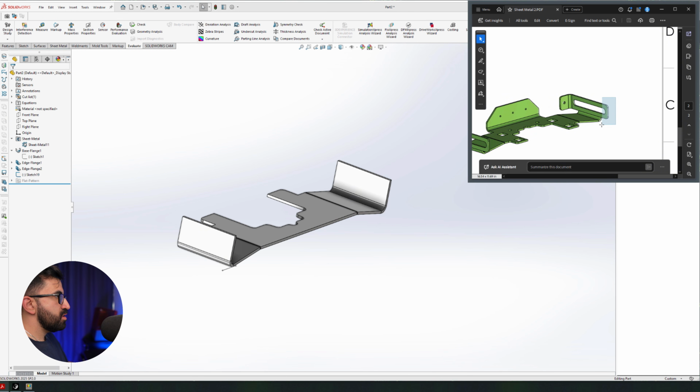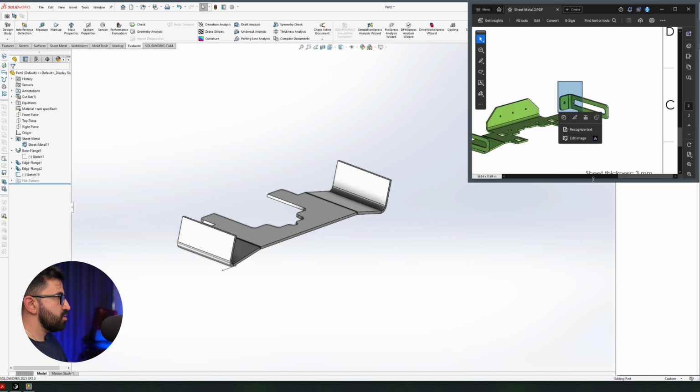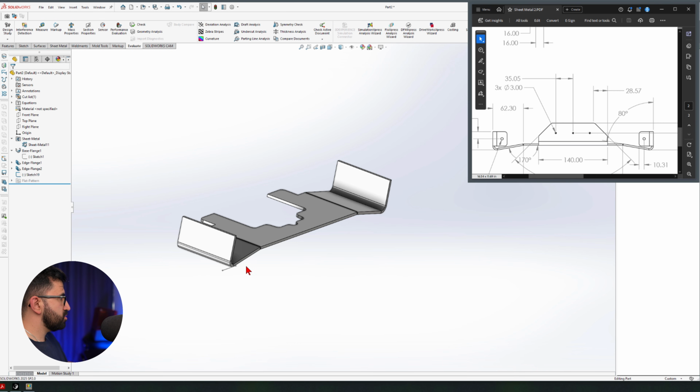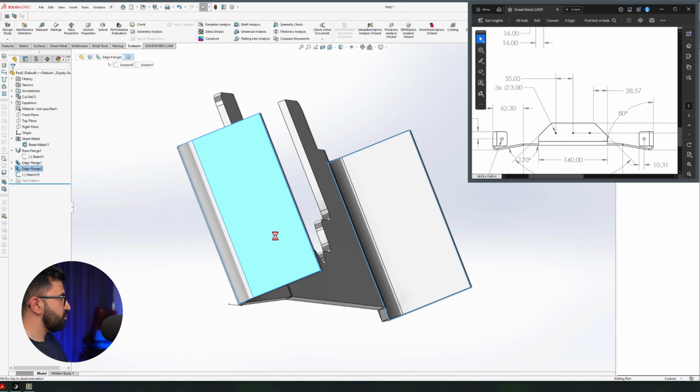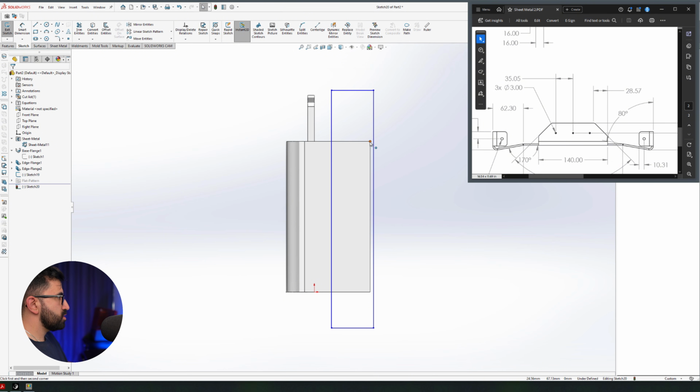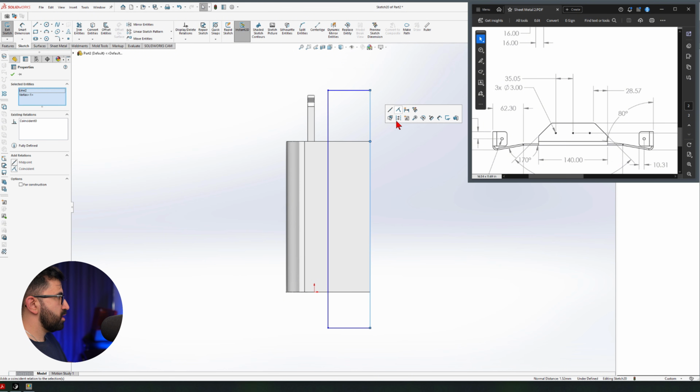As you can see here, there are some extensions extending out of this. So let me just do that. And there will be a correction in the value, which I will tell you. So we want to do that one, draw a rectangle. Roughly like this. Then I'm going to place this point on this line, make coincident like that.